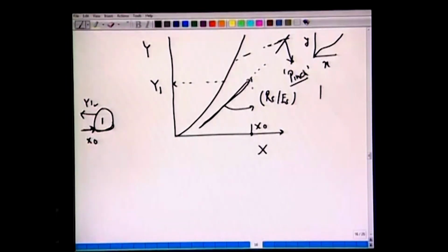In case of co-current, if you recall, we had the equilibrium curve like this, and we had the operating curve with the negative slope, which hits here, where it reaches the equilibrium, so we can say that the two phases are in equilibrium. Here, notice the difference: this operating curve has a positive slope, and still it is possible in some cases that this line may hit the equilibrium curve, depending upon what type of system we have chosen. Wherever it happens, we will have the pinch, zero driving force, and we might require an infinitely large number of stages. Now let us get back to this.